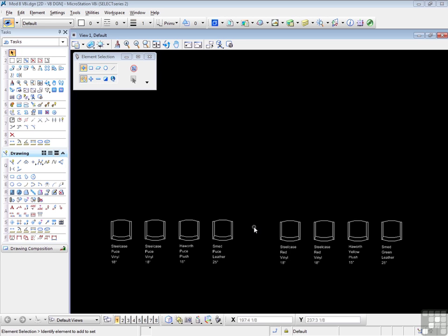In part one, a template is generated which contains the names of the tag sets and the tags to be included in the report. In addition to tags, elements in the design may also be added to the report. The template is saved to a suitable folder, and MicroStation will offer you the default location for that folder, but you can change that if you wish. Part 2 comes when the tagged elements or cells have been identified in the design, and the template is used to generate the report file. And the report produced is a comma-delimited ASCII .txt file.